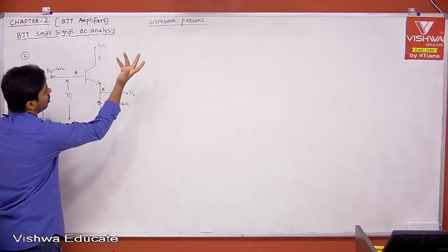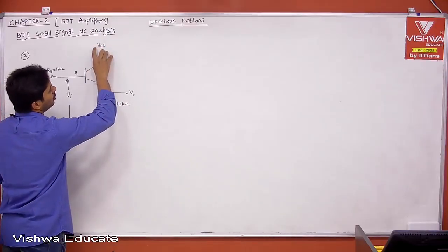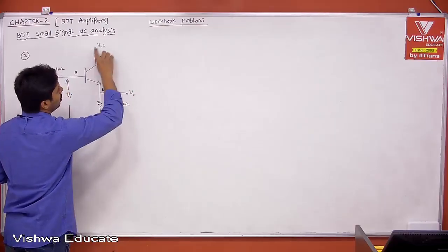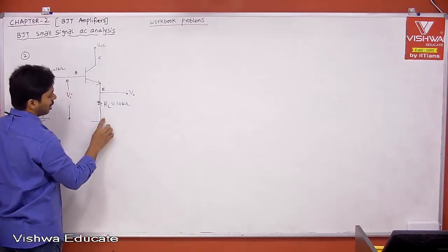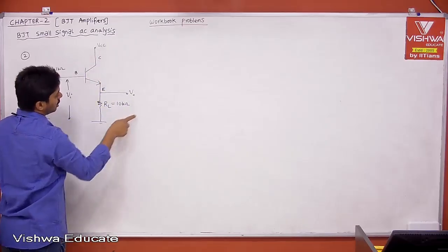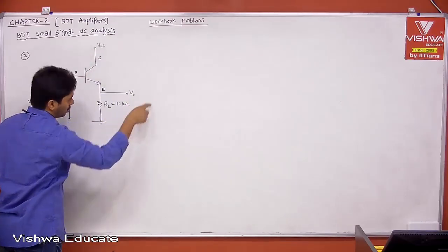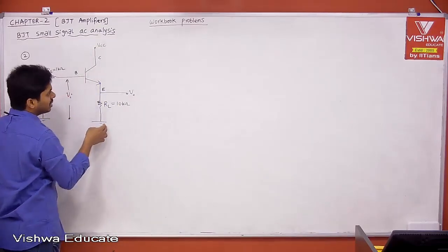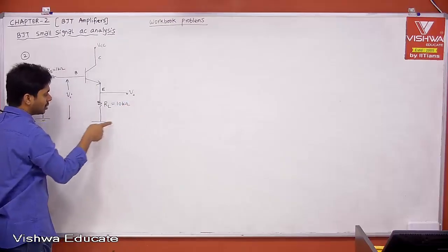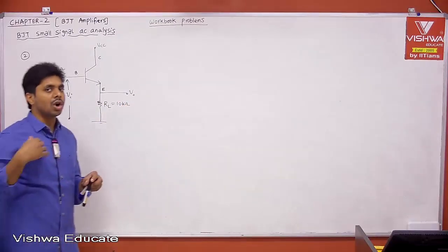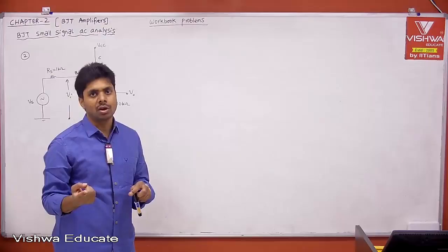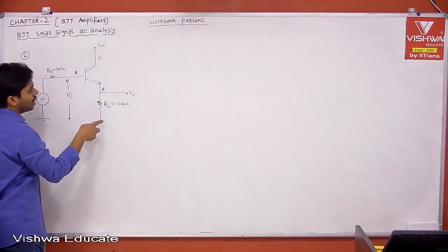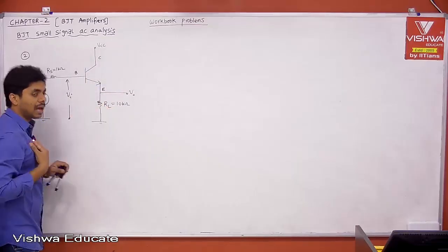That is 0. Therefore, the dynamic resistance is 0, which means we need to replace it with the AC equivalent resistance. This is the battery, which is connected to ground. For AC analysis we need to short it, because we are replacing it with the dynamic circuit. Replacing it with a short circuit, can I say your collector is now connected to ground? Physically we are not shorting this VCC to ground. I am repeating this statement, which I already told in the last session. Then why are we shorting it to ground? That is for our analysis purpose.